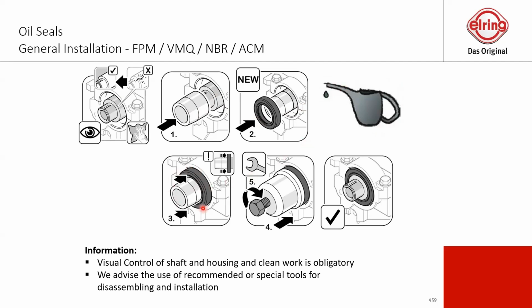That is the right lubrication for this kind of application. And then press your oil seal equally into the housing. If you have a tool, that's recommended. There are also different kinds of possibilities available, and then check if it's sitting evenly inside the housing where it should be. So this is really the classical thing. I think that's nothing special, nothing new for you.